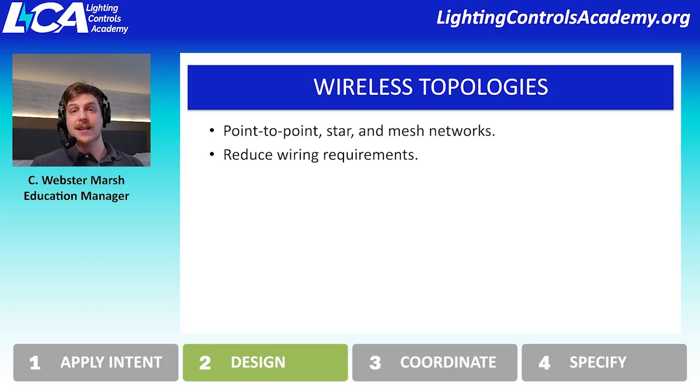Now that doesn't mean that a wireless system is powered wirelessly. Oftentimes we'll still see line voltage or low voltage powering the different devices via wires or some other way of connecting the devices together, but what it really is referring to is its wireless communication.